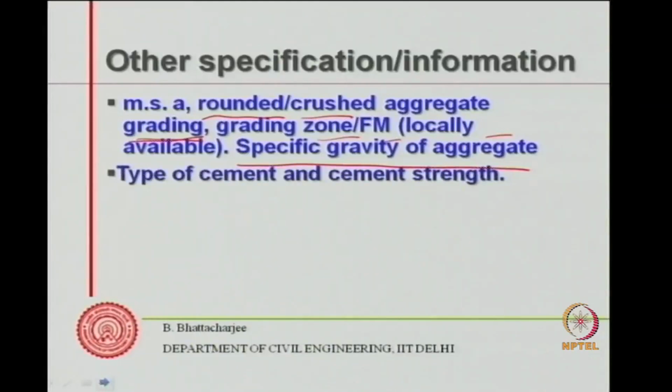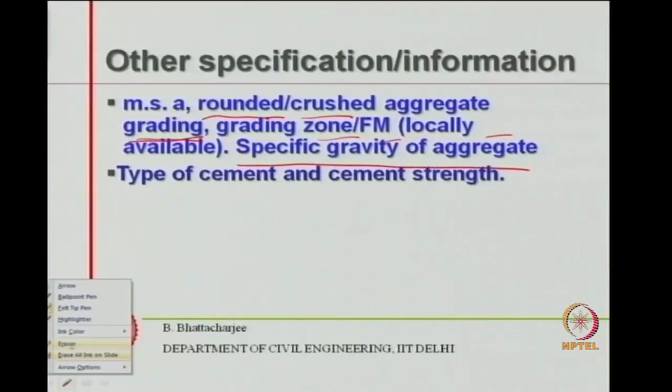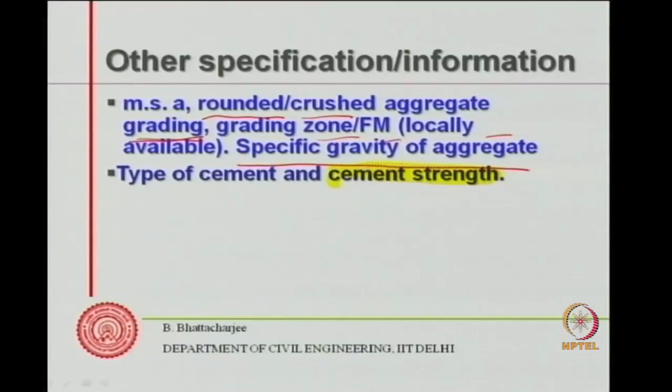We'd like to know type of cement, and cement strength is not a necessity these days. This is not a necessity, but some of the codes might use cement strength as an input to mix design.